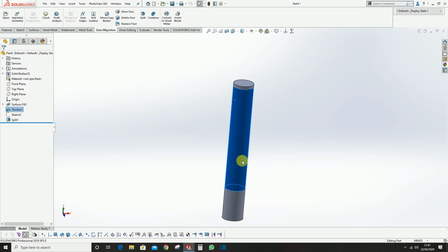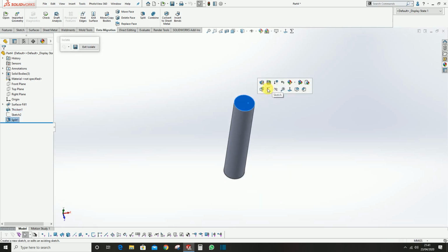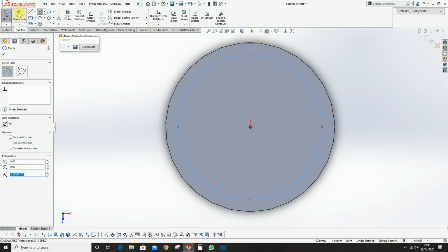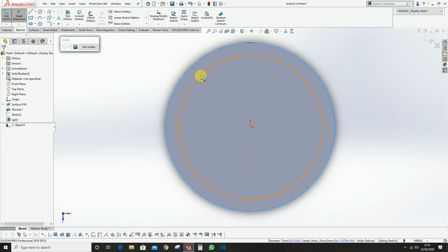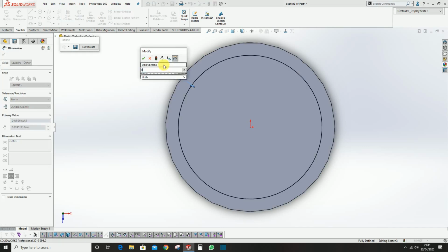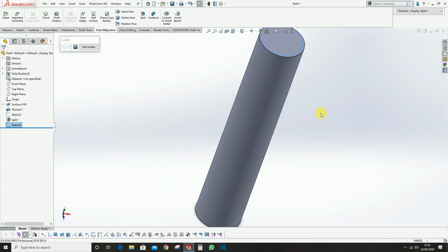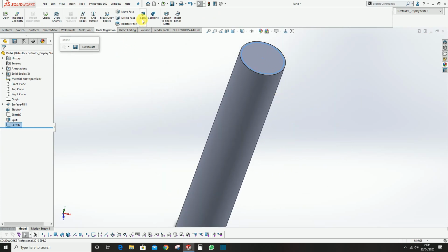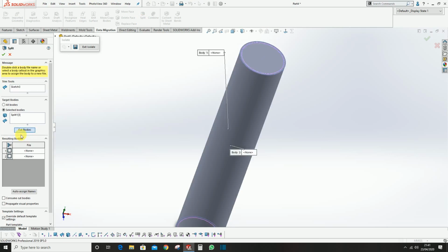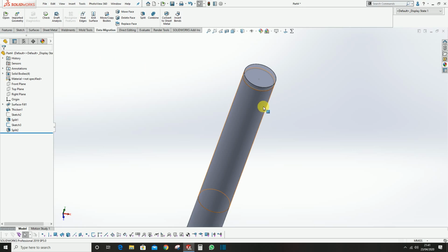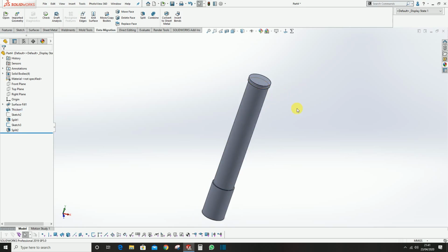And then what we can do is just isolate this body, then do a sketch. Here we are adding a metal plate. We can give the metal plate a thickness of 0.5. Then again we can use the split option, so we will get a separate body like this. Also ensure we don't tick the consume cut bodies. Then we have this body and all these three bodies.